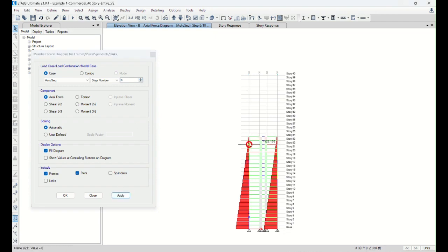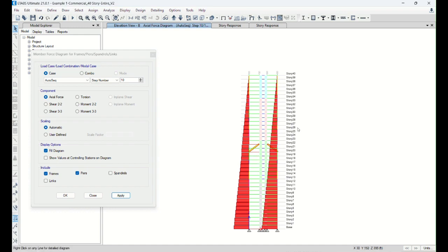But since in this model we define this outrigger as a part of a group, right? We exclude these outrigger elements during the construction. So this is part of the analysis tool. We try to avoid that; outrigger construction will be delayed, right?